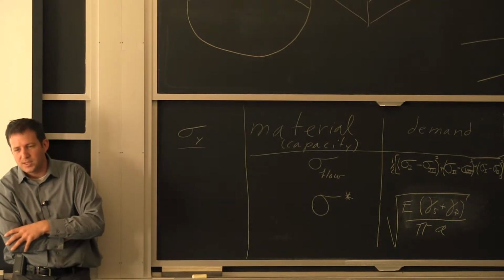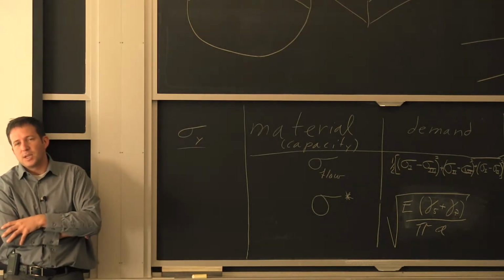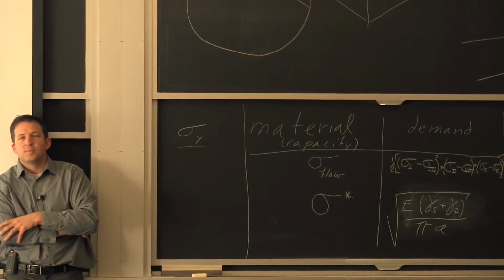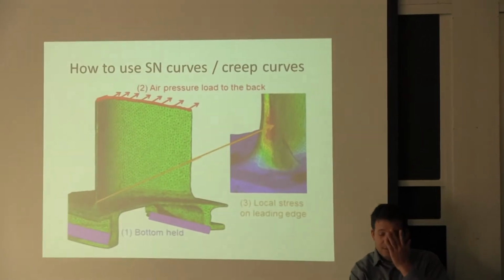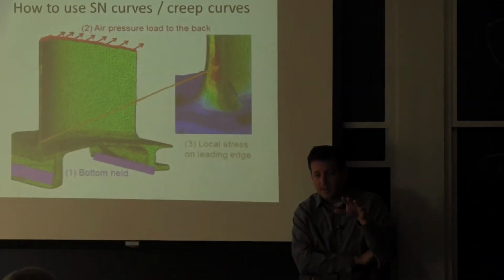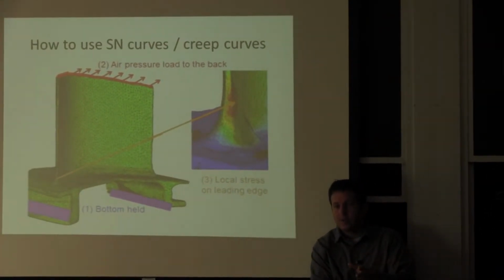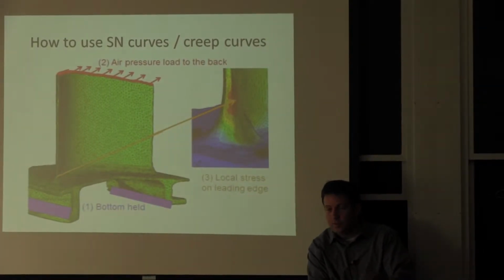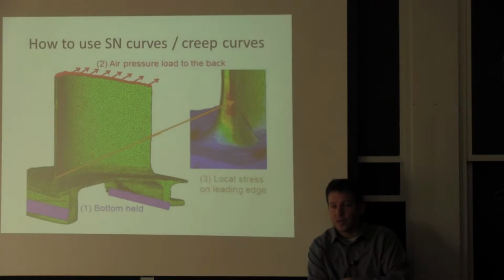I don't remember. It depends on the frequency and stuff. But if it's considered a stress life, typically at 10 to the 6 cycles is an area where you can retire it, and you anticipate if you were to keep it, that it will continue to work fine for another period of time.